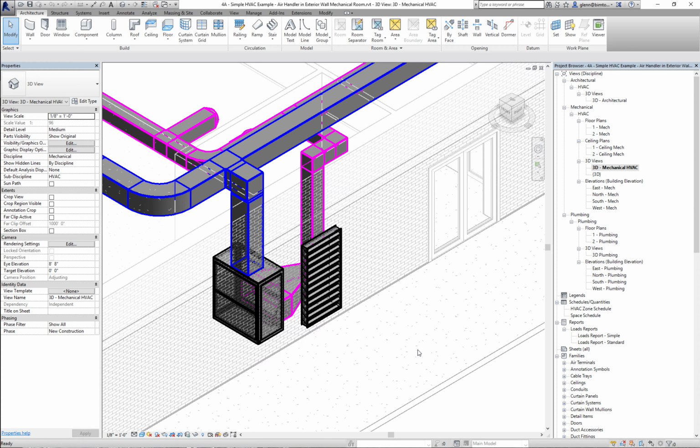In this mechanical room, which is down on the first floor, there's a louver that's basically allowing the cool air to either come in and be used as the return air. I can also exhaust out through a set of louvers, so it's okay to have it on the outside of the building. You don't want to have it on the rooftop.